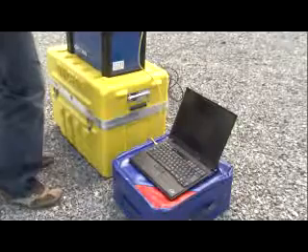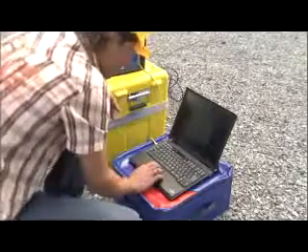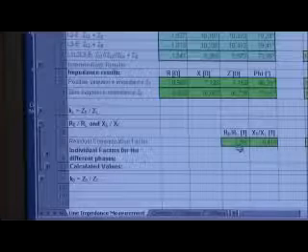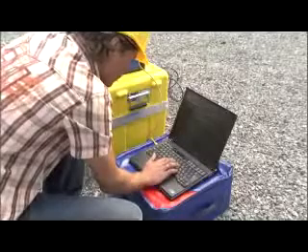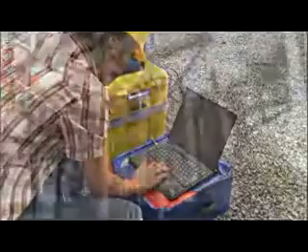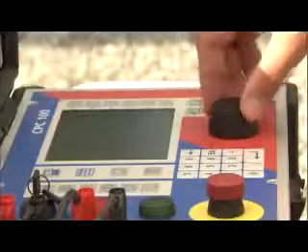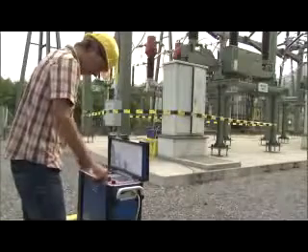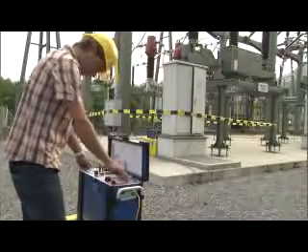The resulting file is loaded to a PC. In MS Excel, the K-factors can be displayed in various common formats. The costs for the K-factor measurement are small compared to risking the enormous costs of a possible power outage. To accurately detect a fault, your relay must have accurate K-factor settings. This requires precise measurements of the impedance of the line and ground return path. CPC 100, together with CPCU1, is the best tool to measure it.